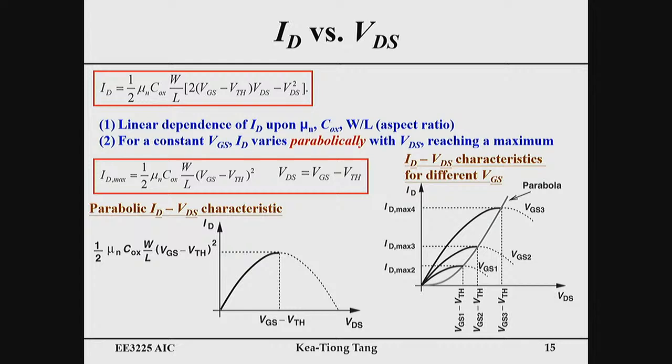Okay, it actually depends on the value of VGS. If we increase the VGS, the maximum happens at larger VDS. And if we connect these dots together, it's another parabola. Okay, this is another parabola.